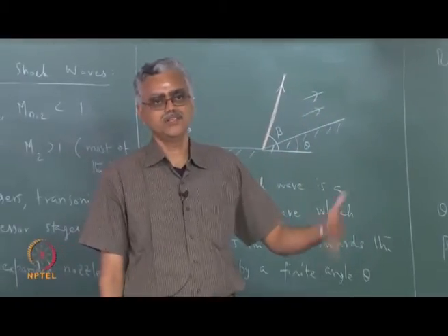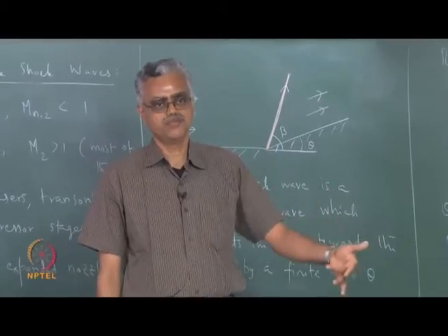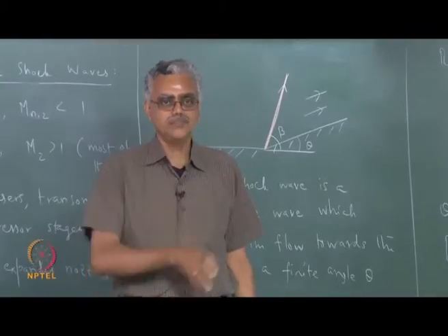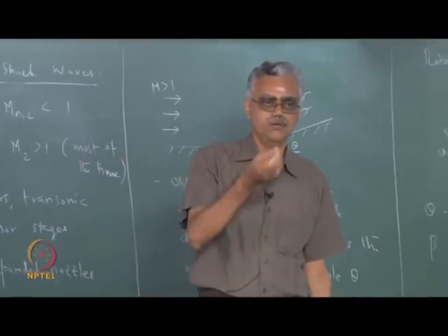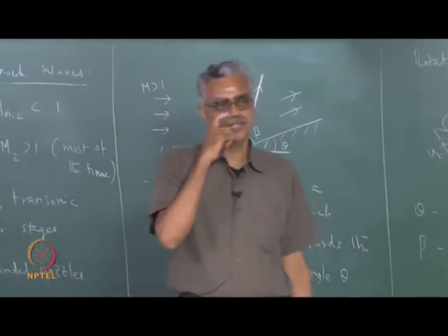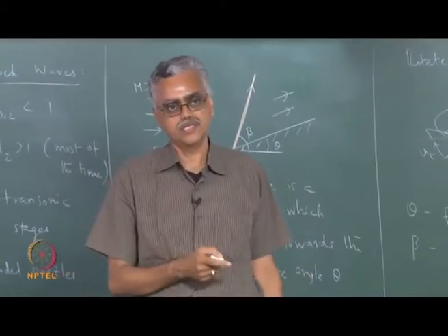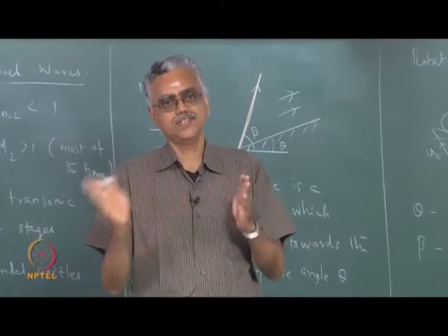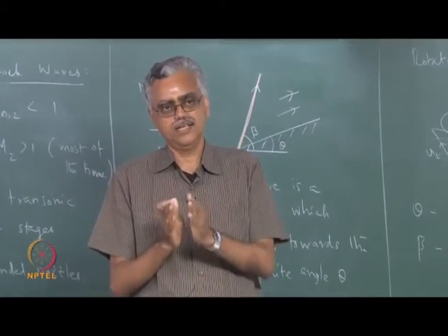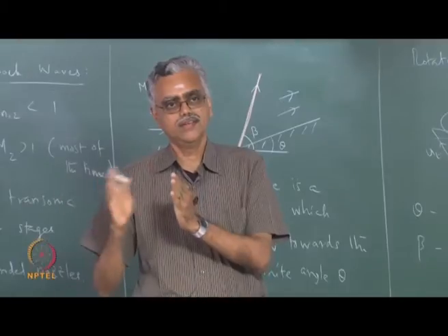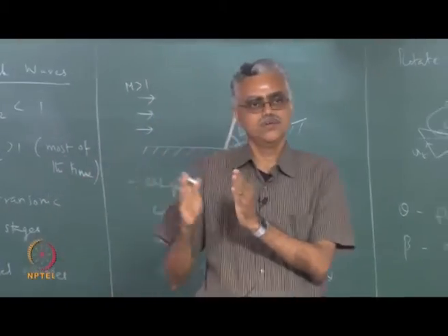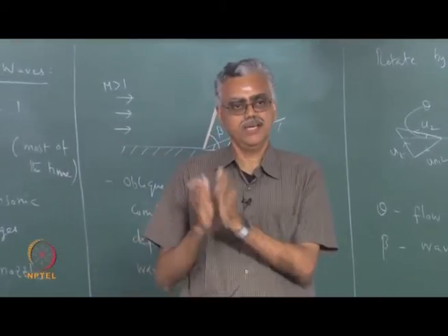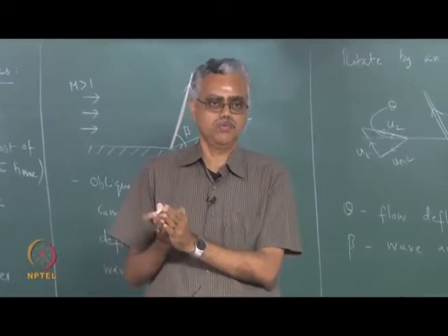The smallest possible is an acoustic wave, which moves with the speed of sound. So, there cannot be anything less than that. A wave solution, as we discussed in our earlier chapter, is permitted only if the speed is sonic or supersonic. The nature of the governing equations is such that the equations are hyperbolic when the velocities are supersonic.